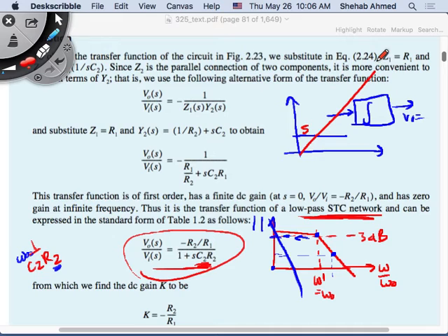This ramp, does it stop? Your input does not stop. Is the ramp going to stop? No. Which means that the gain for the DC signal, when you pass it through an integrator, is infinity. It keeps going to infinity. Well, fine, the op-amp will saturate, that's fine. But this is what this means. This is a better way to explain than Laplace. So hopefully this is clear now.